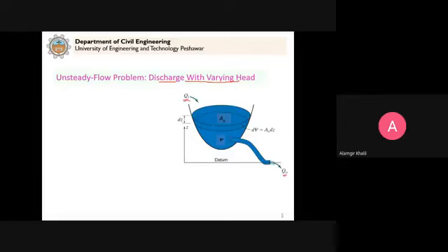Now in this tank, the liquid is contained. The level of the liquid is denoted by Z. It can be denoted by H, as you might have done in the case of orifices and notches, where you calculate the discharge, and the head was denoted by H. But in our textbook, this water level is denoted by Z. So we will stick to this sign convention: Z will represent the water level in a tank or in a reservoir, and the change of water level is denoted by dz. This Z will be with respect to a datum that we have to select.